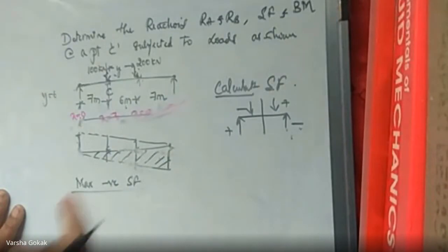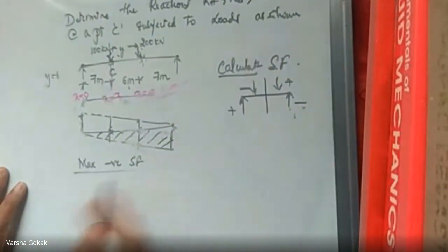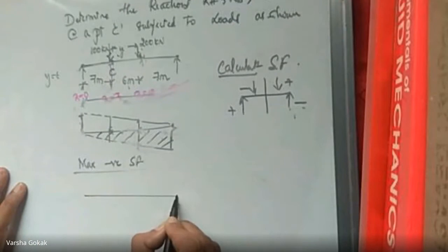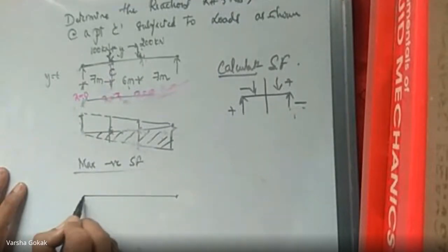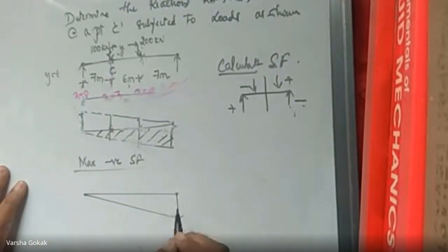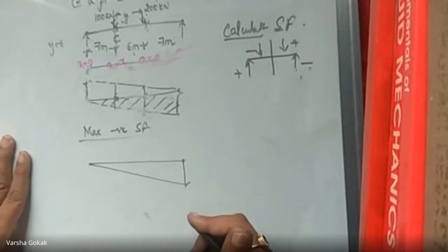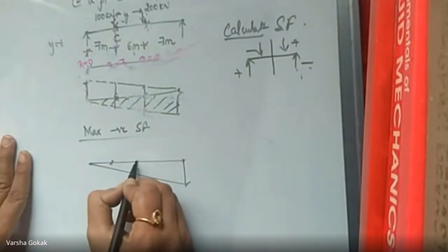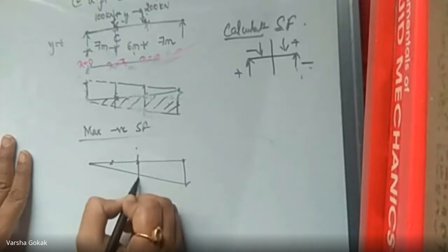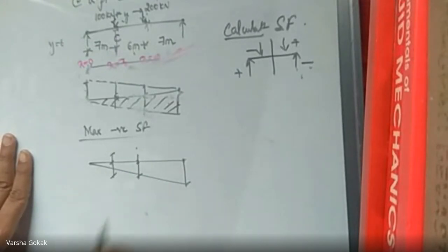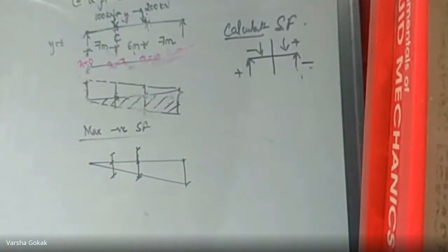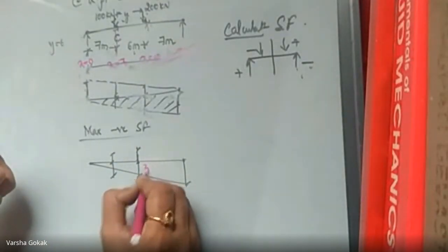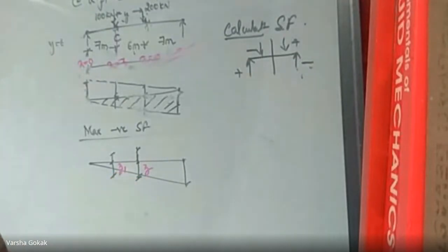So I will have to place the loading such that that y value will be maintained. That is 6. Okay. So if I draw this negative diagram like this, which is going down, I will have to take ordinates at these levels. I need these ordinates and I will name them here. I have to calculate the ordinates. So I'll call this Z and I'll call this Z1 ordinate.